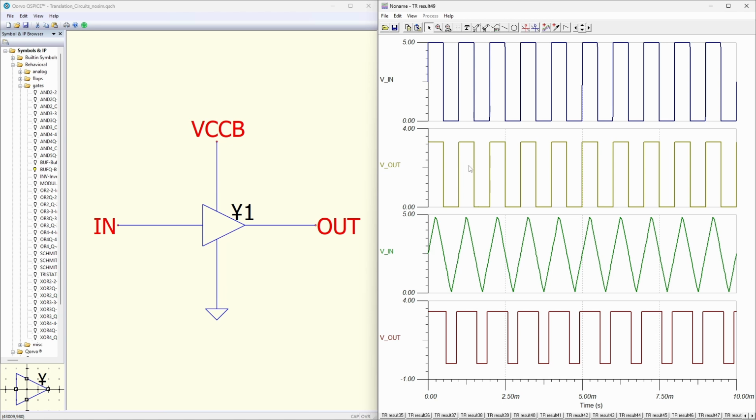One thing to mention is that generally speaking, CMOS devices don't like slow transitioning inputs. My simulation shows a very perfect output from a triangle wave input. Many times you'll see an oscillation on the output if an input is as slow as this. So if you do have a slow input, generally speaking, you'll want to choose a Schmitt trigger device like the LVC1G17 instead of the LVC1G34, which is just a standard CMOS device.